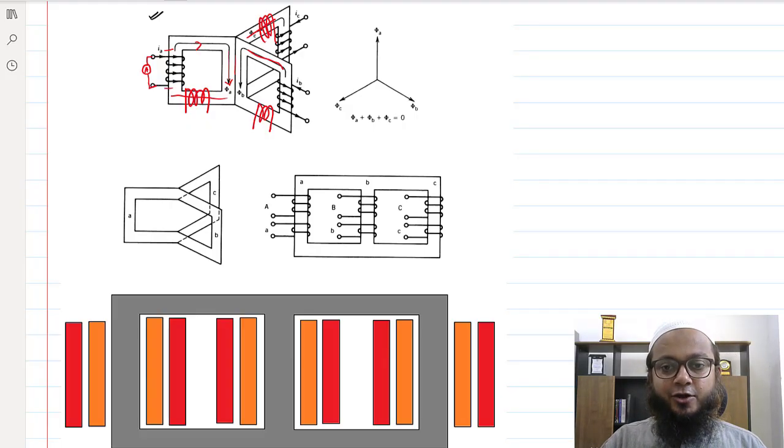As we know, in a three-phase balanced connection, if you remember, star-star, we don't need a neutral wire to be connected there because the sum of the neutral current was 0, right? IA plus IB plus IC is 0. So we said, okay, we won't need this neutral wire, and we have altogether eliminated that neutral wire there, in a balanced condition, star-star.